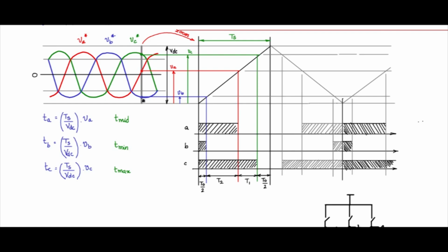So this is T0 by 2, and this is T min. T min here is negative. Most of the time T min will be negative, because wherever you make the window cut, the minimum time will be lower than 0. So we just add this absolute value plus T naught by 2, the whole DC will shift, and the 0 line will come in here.